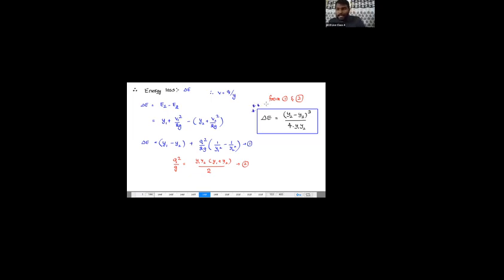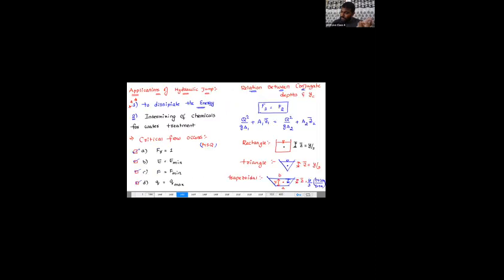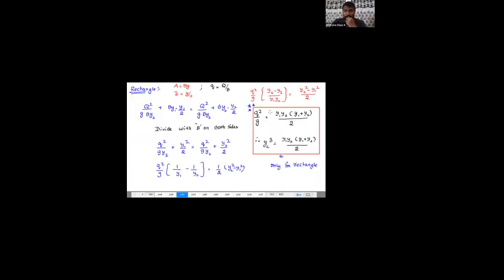So once we get the relation between the conjugate depths and the flow rate or critical depth, then from one conjugate depth I can find the other conjugate depth. For example, if we have a flow rate and a pre-jump depth, I know the flow rate Q and I have a pre-jump depth. Can't I find out the post-jump depth? What is the post-jump depth?